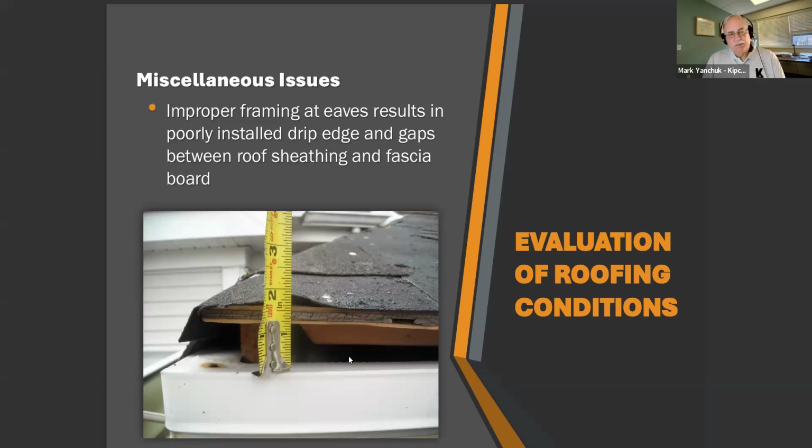When you're doing any of these roofing projects, you want to make sure that there are no gaps. It is very commonly seen that fascias don't close up the gap properly. Any gap, even as small as this, is an invitation for birds, squirrels to get into your attic, or even hornets.